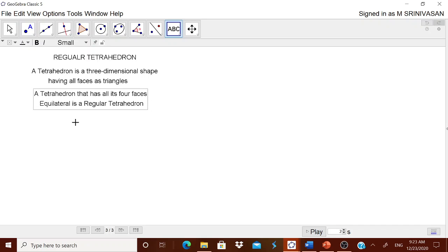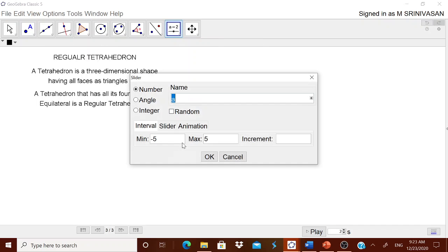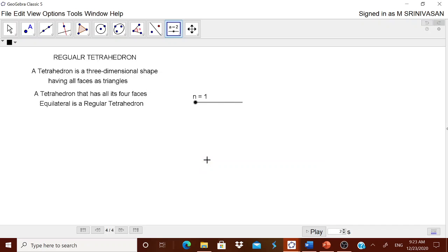For that, the idea is very simple here. If you want to have a single length of it, then you can have. But normally the length you are having may not be an integer. If you want the length to be an integer or as per your convenience, let us go for the slider. In the slider, I am having this integer. Therefore, I will have it from 1 to 10 and increment as 1. It's not required actually, it is left to you. Suppose you can have this increment as 0.5 also. It will become 1, 1.5, 2, 2.5 and so on.